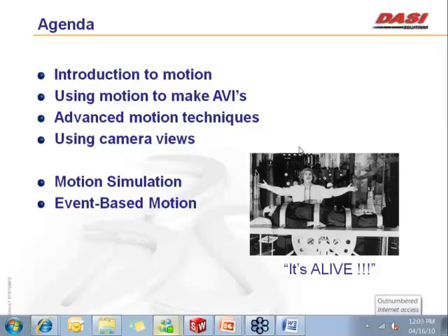This actually works inside of part documents too, if you simply want to switch between configurations and show an animation of that. I've used it in cases where you want to show how maybe a sheet metal component is folded or flattened. You can walk through those configurations using the record function and save it off as an AVI.